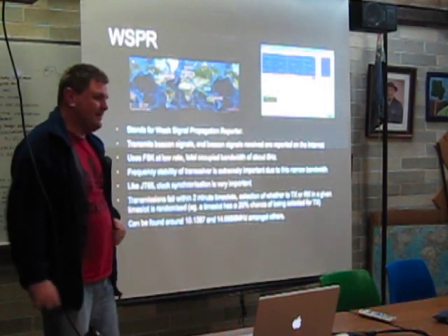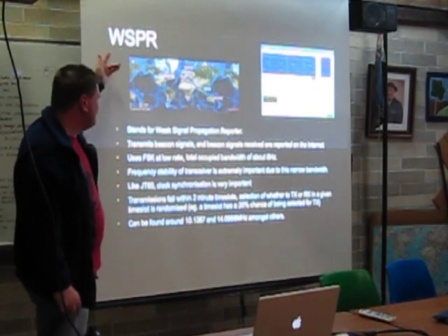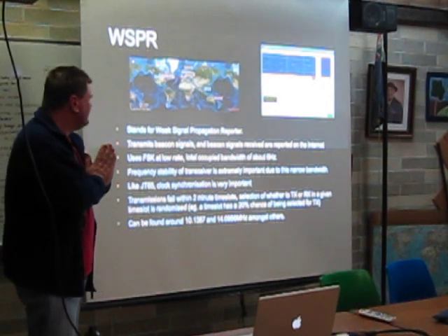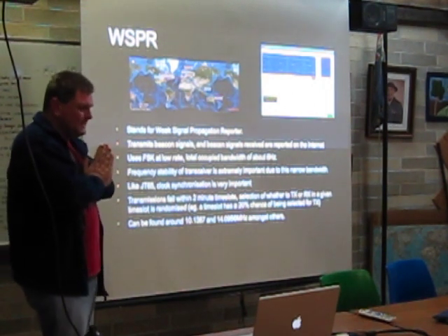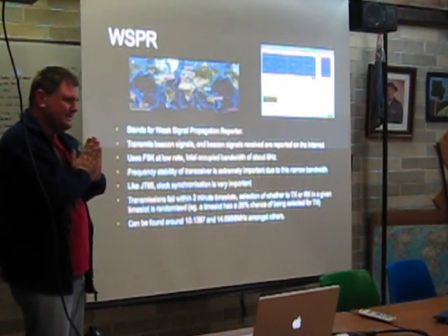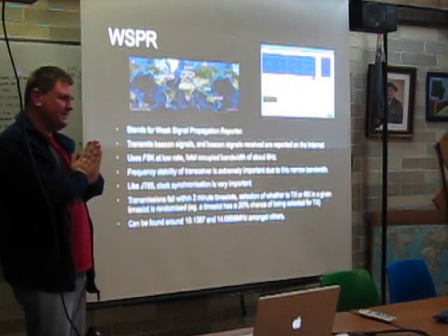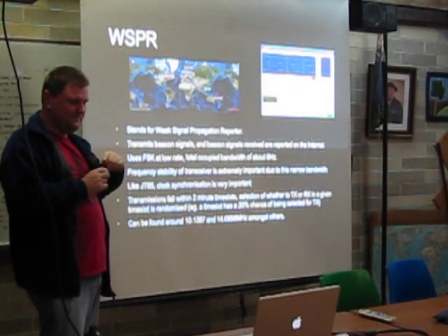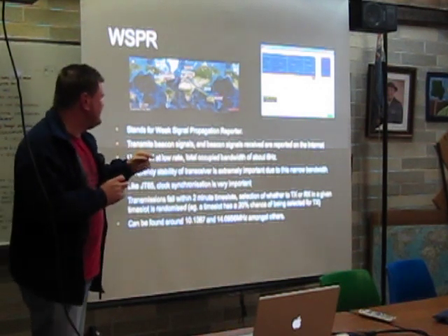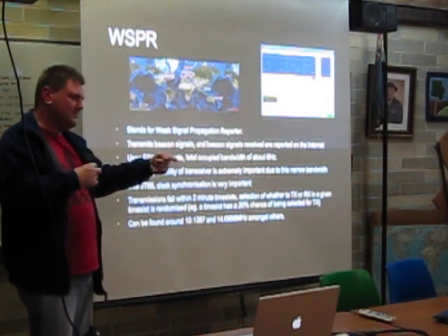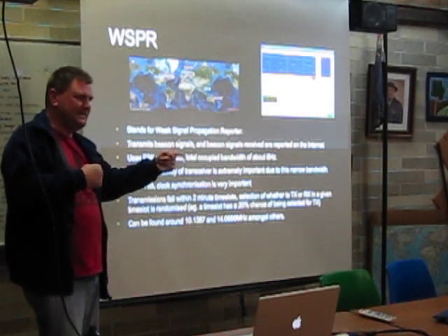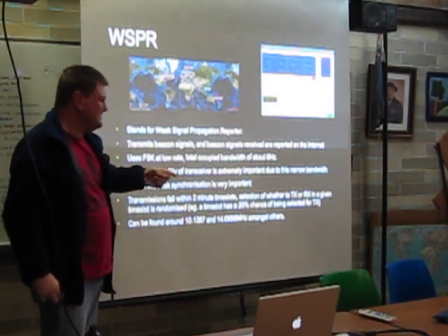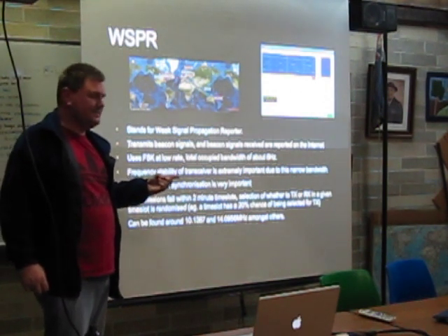Whisper is written by the same guy. It's pronounced WSPR. With this mode, it's very narrow bandwidth, even less so than PSK31. It's a 6 Hz bandwidth, so that means that the rate at which you can modulate the carrier is very slow. And here you transmit for 1 minute 54 seconds, nearly 2 minutes, and basically all you're transmitting is your call sign and grid square.